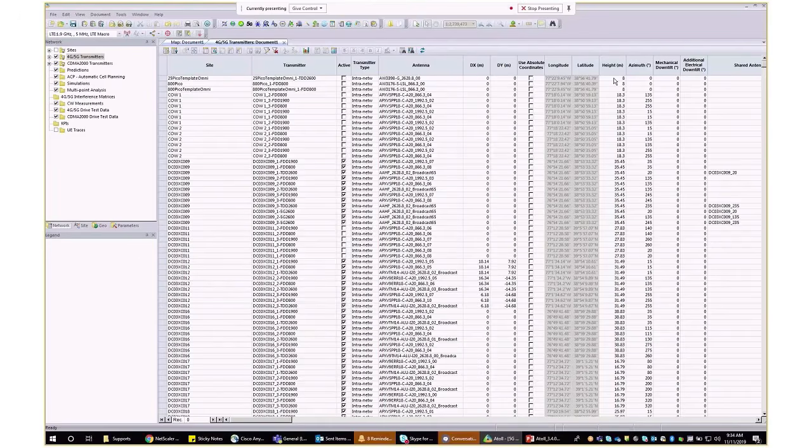Same way, if somebody else is making any changes in Atoll, and if he doesn't archive the data, it will not show in the server. Second thing is that if some other guy made any changes in Atoll and he archived the data, but if you don't refresh your Atoll after he has archived his data, it will not show in your Atoll.